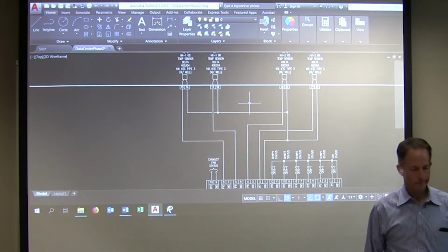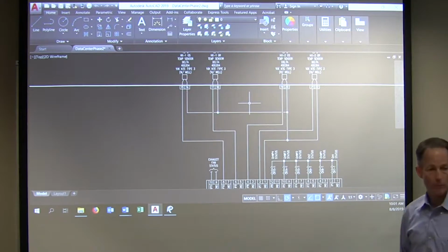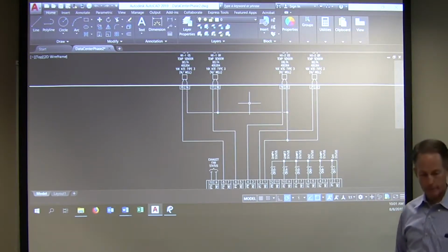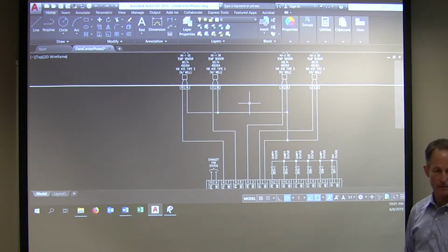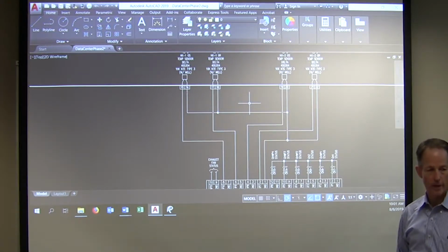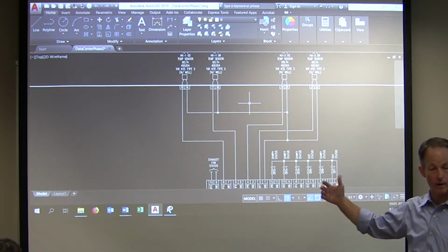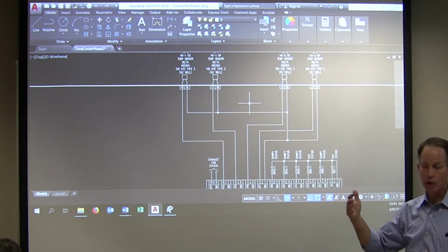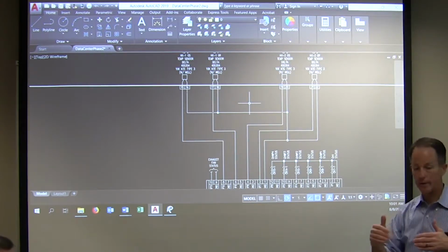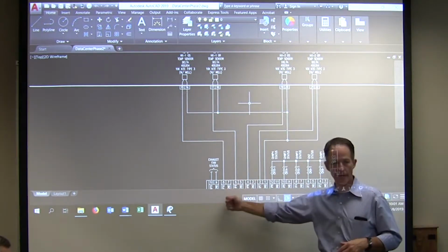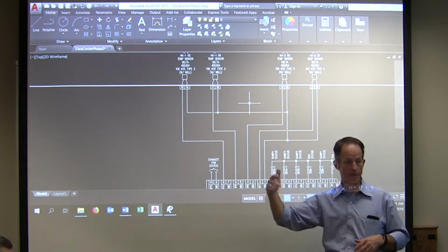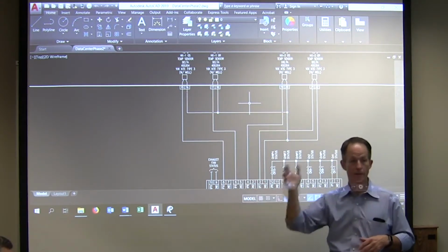But I've also run into where somehow the programming got glitched inside of the board. So it's not physically the board's problem, it's the program. It could be showing the controller's programming firmware, showing the temperature, but the program it's supposed to be is not. Negative got changed to positive or something. So before we go rip out the controller, we ask our friendly neighborhood control guy, can you go trace this point in software that came through on that input, trace it back and verify that I'm really getting that point to the graphic.